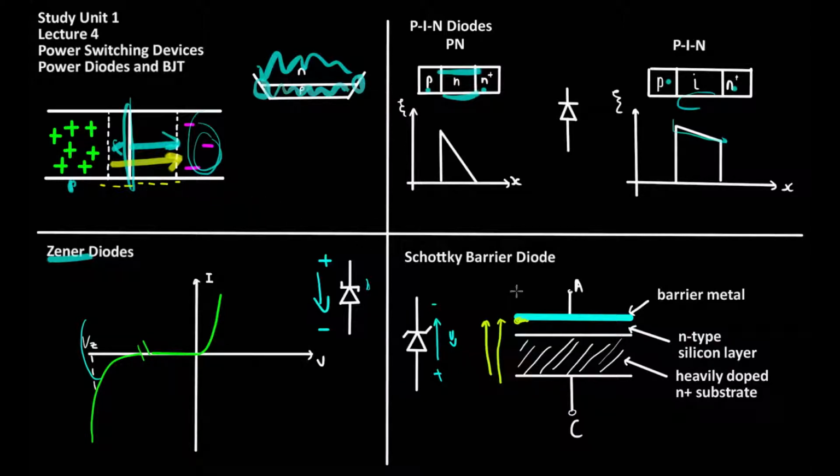This is not the case for the Schottky barrier diode. In the Schottky barrier diode case, the reverse bias current is caused by majority carriers which overcome the barrier potential which exists at the interface between the metal and the silicon. An advantage of the Schottky barrier diode is that the electron carriers are swept across the region and then combine in a metal layer. This means that the Schottky barrier diode is able to switch incredibly quickly.